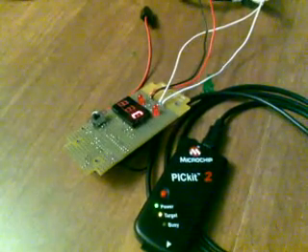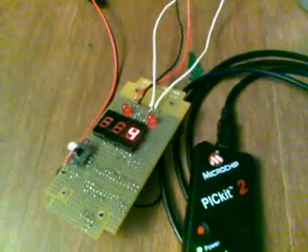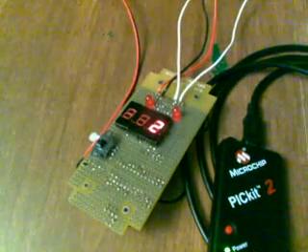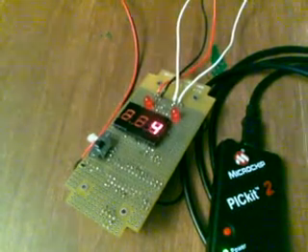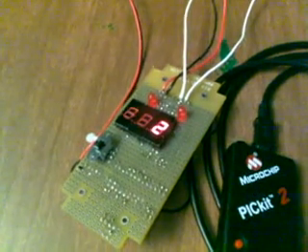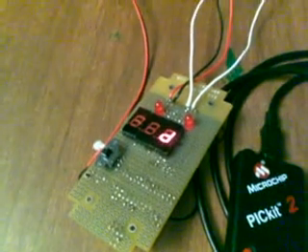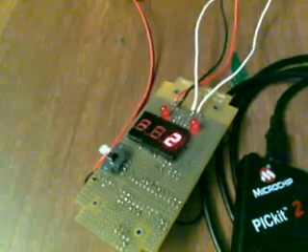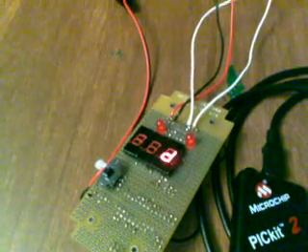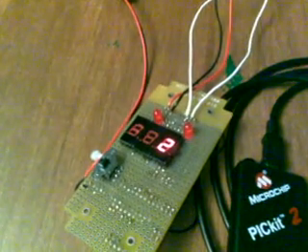So a number of compromises were made in the hardware here. This ends up only really being a proof of concept. Originally I wanted 4 displays so I could display a 4-digit number for 1200 pulses. And then I realized that I ran out of pins on my microcontroller. So I used 3 7-segment LED displays and was going to display the number in hexadecimal. That works great. But then I realized that actually I need 12,500 and I don't have enough pins for that.